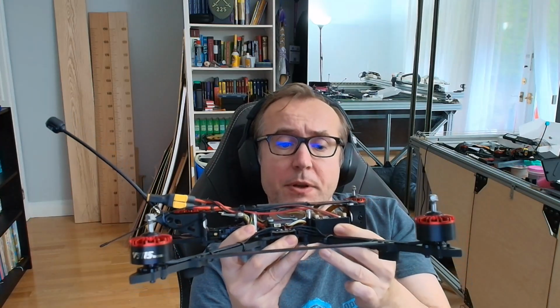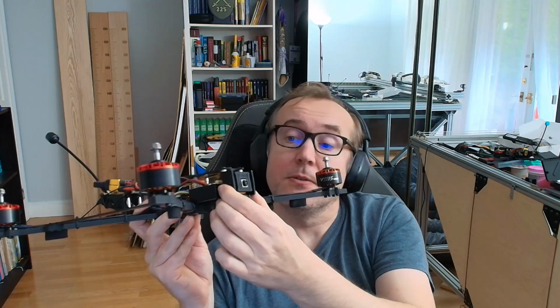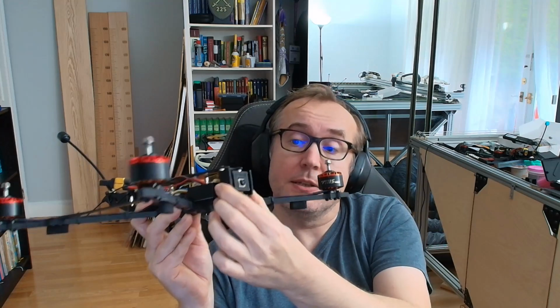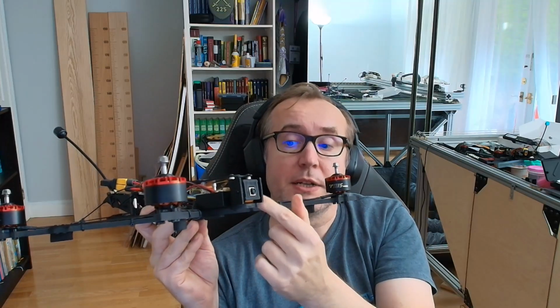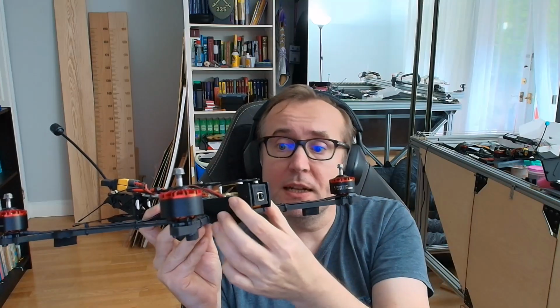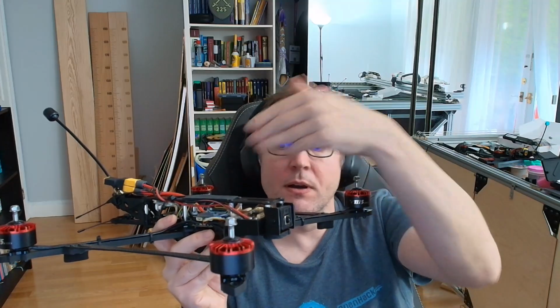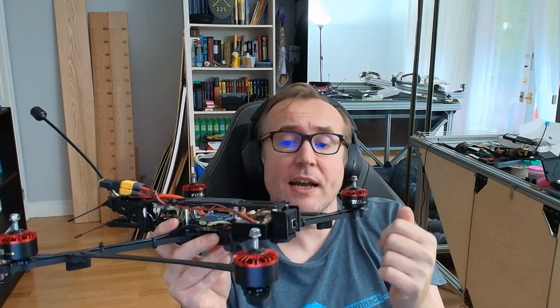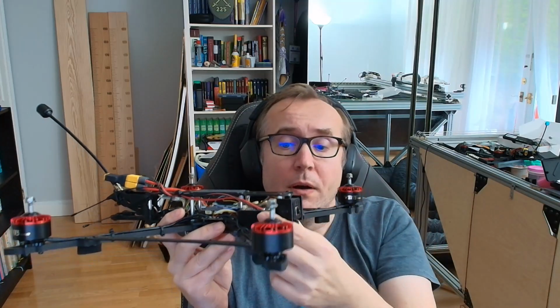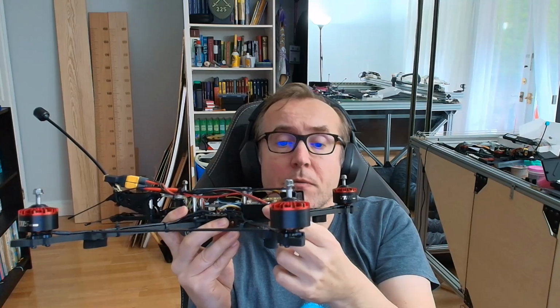Moreover, since we have a companion computer here, we have the ability to connect a digital camera to it in order to have video in much better quality rather than getting video from another camera, for example. After that, we can pre-process this video, implement our algorithms, and send video to the flight controller using the output that we have on the Raspberry Pi Compute Module 4. That is our companion computer here for today.